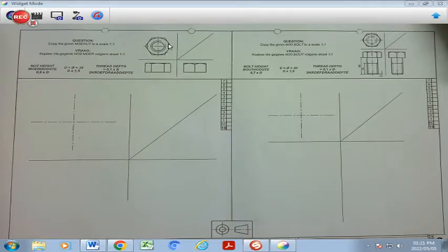You will also find that the nut has a double circle, which would be classified as concentric circles, which is basically inside of the 38 diameter. That double circle refers to the internal threaded part. Then you will have a third circle, which is on the outside, which is the bigger circle.